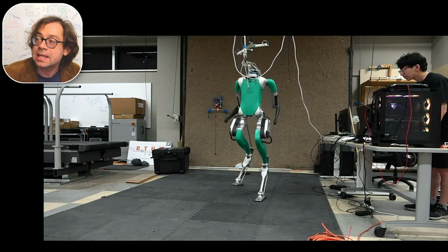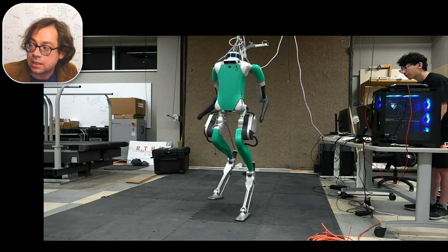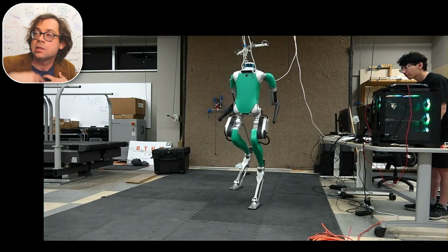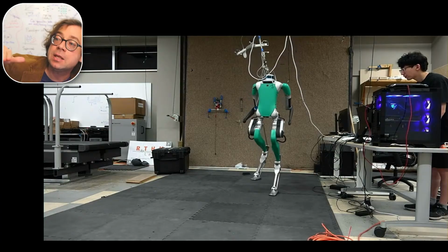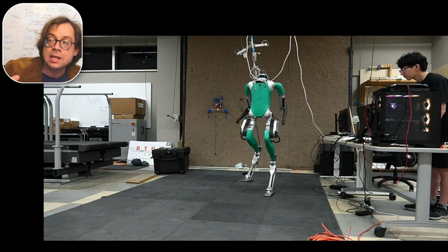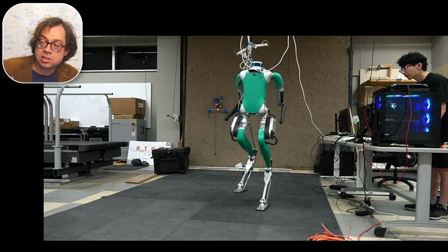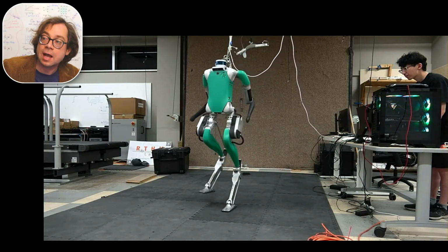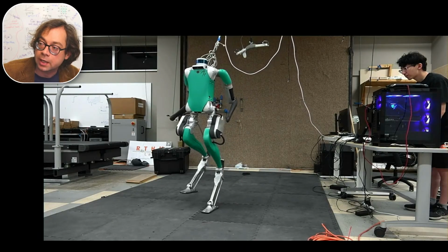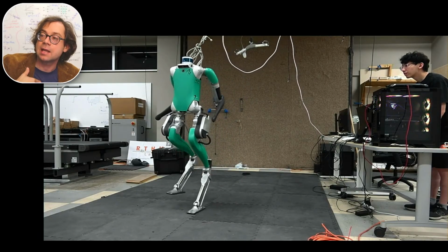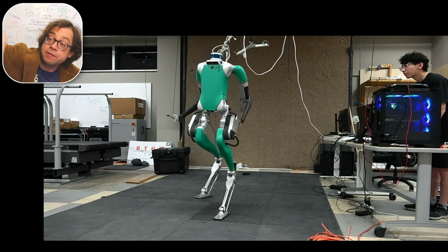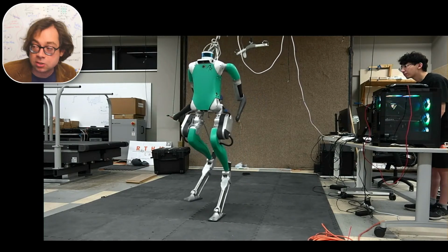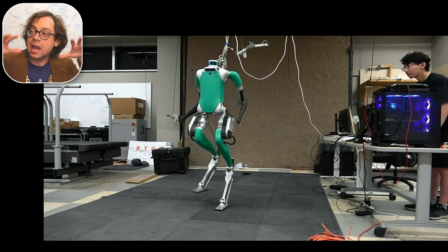Tianza, on the right there, is designing the task space targets. He says, I want the center of mass to move to this position and that position, and a PD controller is driving it back and forth. And yes, the stepping around makes it harder. There's a model predictive control element of this as well, but that's higher level. But every thousandth of a second, it is running a quadratic program, and he's saying, I want my body to be here and rotate in this direction. I want my feet to be in this position. Move my feet there. Those are its task space targets, the center of mass of the body and the feet.